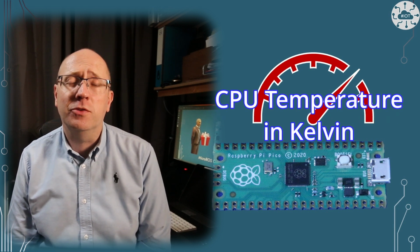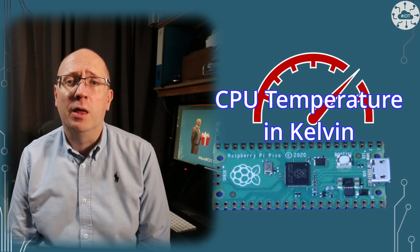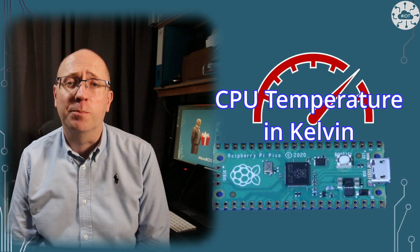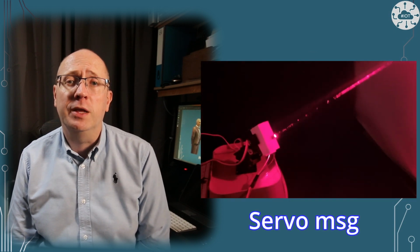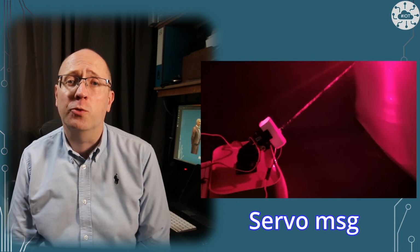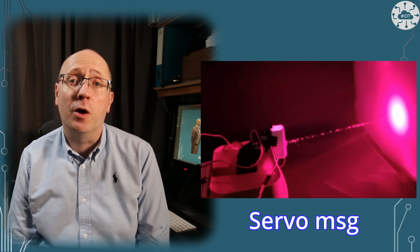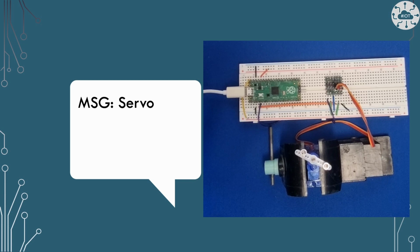Using specific message types helps in making the robot type safe, understanding the context of what is happening and documenting our system. In this video, I'm going to show one approach to creating a custom message and publishing custom messages from our Pico. I'm going to write a new custom message for our Pico to use with the Micro ROS. That message is going to control a servo.